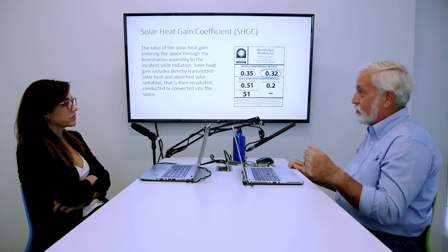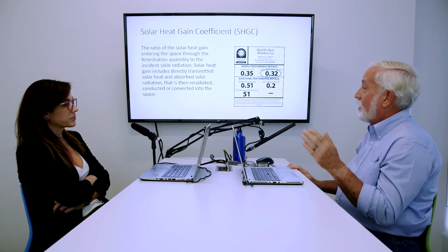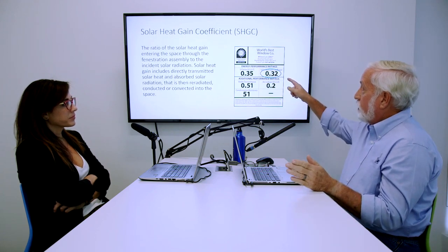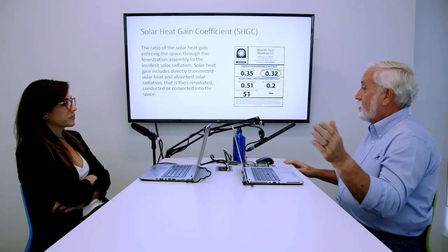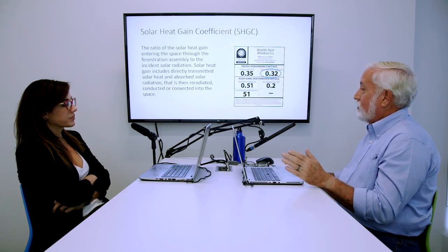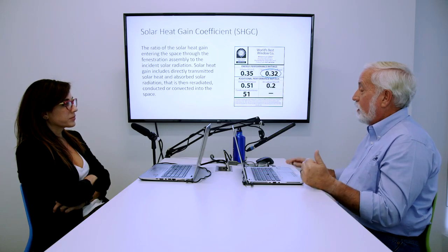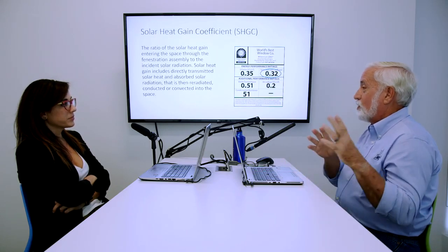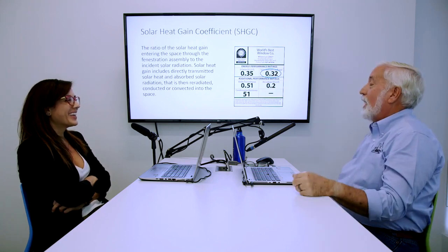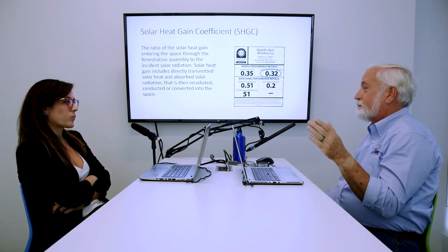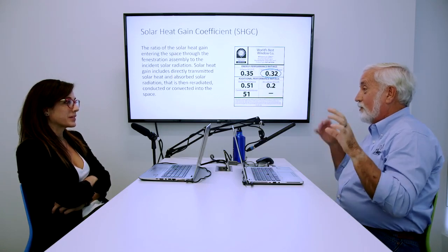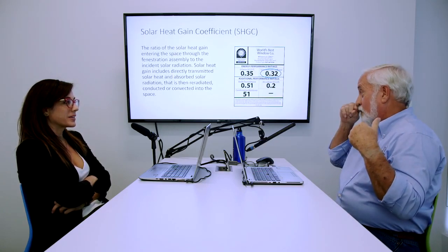Now on your south-facing glass, if we have a low solar heat gain coefficient, we block some of that heat that's available. Now that might cause a challenge though. My previous home had my office, my study, facing south, and it had big tall windows. In the wintertime, what would happen is that room and the living room had south glass, and so they'd heat up.